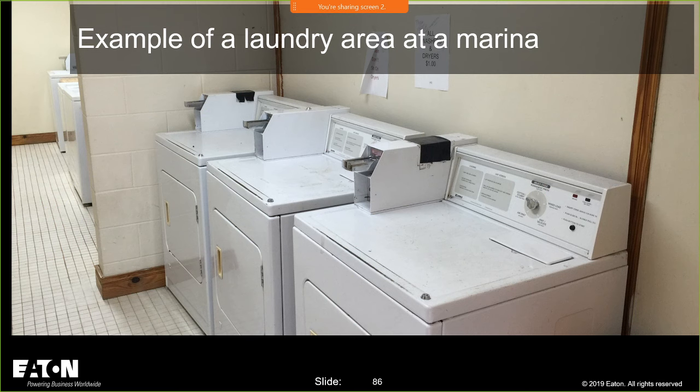And there's an example. Any of those receptacle outlets are going to have to be GFCI protected, and more often you're probably going to put a circuit breaker in. And in some cases on the three-phase ones, like up to 100 amps, there's no circuit breaker that exists for that. There's no circuit breakers, there's no receptacles that exist. So you'll probably have a shunt trip circuit breaker, putting a GFCI relay in there, or not shunt trip, a breaker. You usually pass it through that relay, and we have products for that as well. So we have solutions to solve those problems up to 100 amps, no problems.